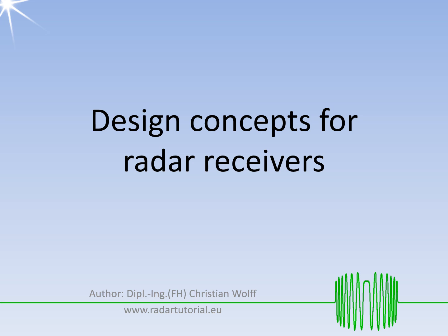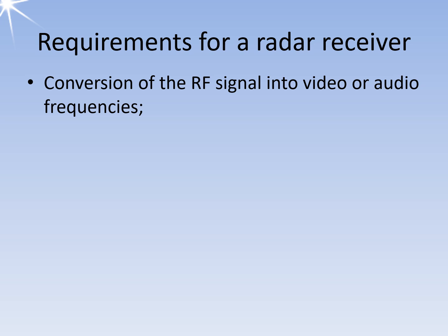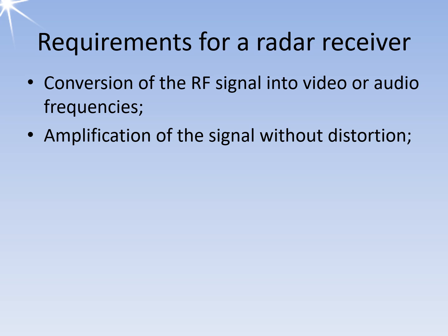This video explains the design concepts for radar receivers. The requirements for a radar receiver include various specifications that ensure optimal performance and accuracy in detecting and processing radar signals. The conversion of radio frequency signals into video or audio frequencies is essential. Video frequencies are used for imaging radar, while audio frequencies are utilized for measuring speed using the Doppler effect. The radar receiver is intended to amplify the received signal with low noise while preserving its waveform.